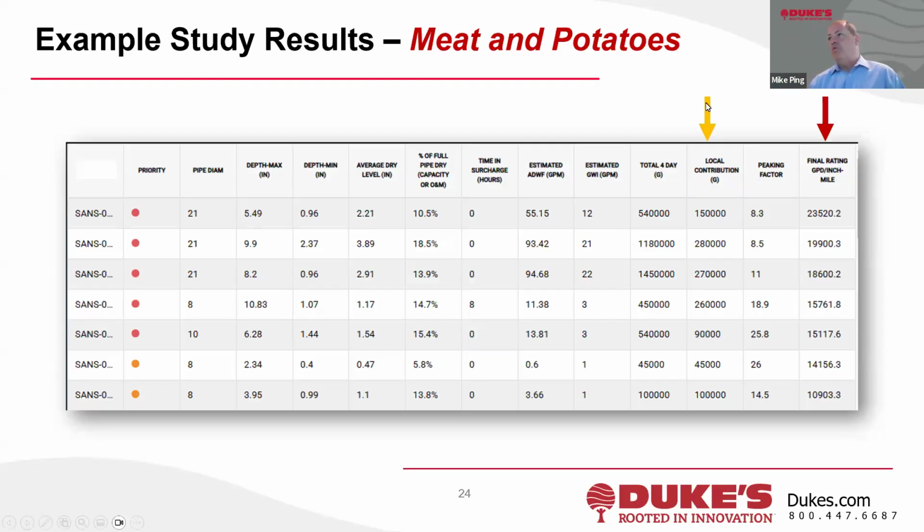So where this orange arrow is, it's the total local divided by how much pipe is in that specific area. So we do that in inch-miles, inches of diameter times length of pipe. And look, these areas aren't all the same amount of pipe, so we try to even it up with the denominator there, inch-miles.